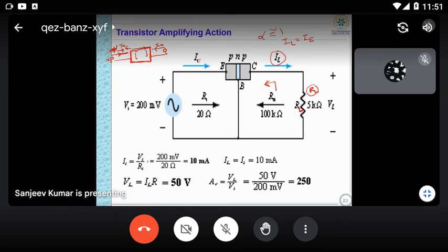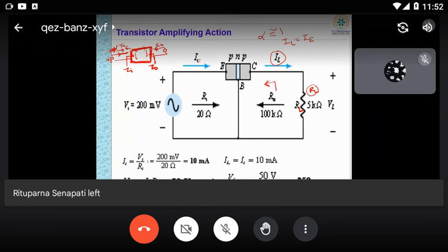Now in this two-port network, if I'm measuring the impedance of this network, this is known as Zi. And if I'm measuring this impedance, that is Z0. I will also tell you, when you do the equivalent circuit of a transistor, this is the impedance of this box, this two-port network, or you can take it as a transistor or any device.